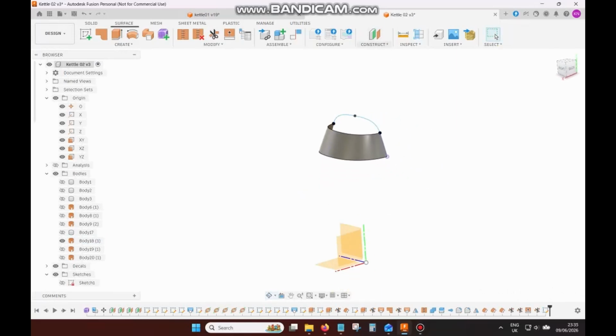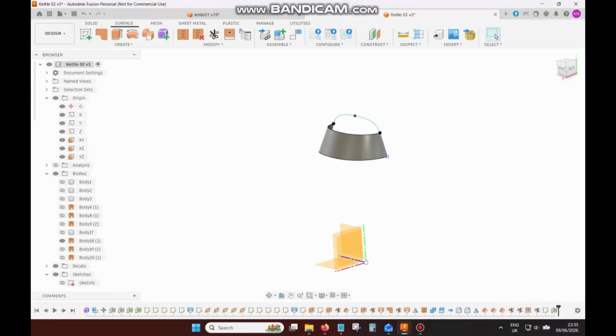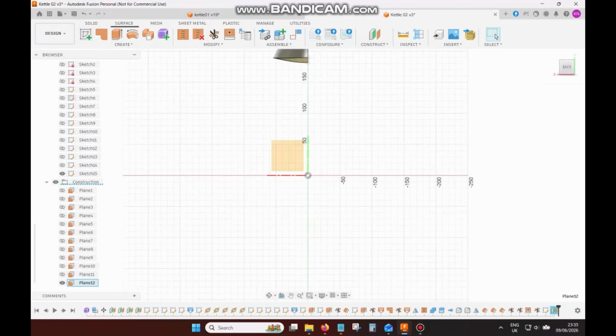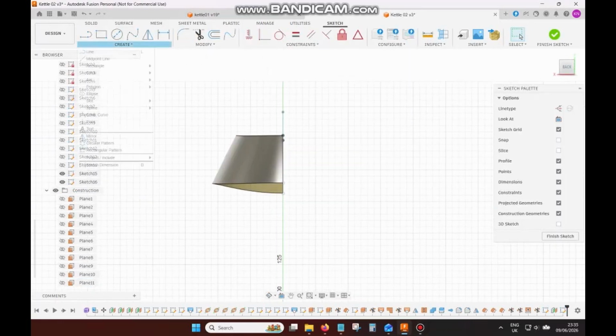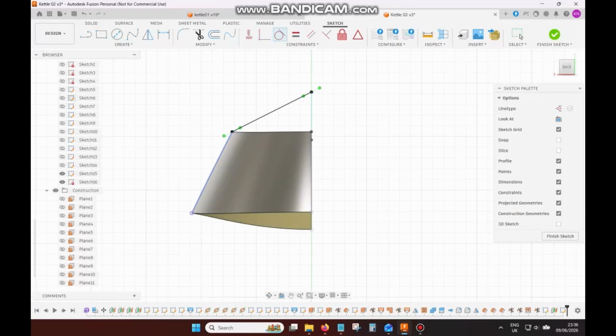I'm now putting a plane to create a profile that goes sideways, because ultimately I want to make a kind of loft surface to create the top of this stopper. So I have created a plane that is parallel to the front and back plane, but using the dot on the spline, just for tidiness' sake, I kind of want to join up things where I can.